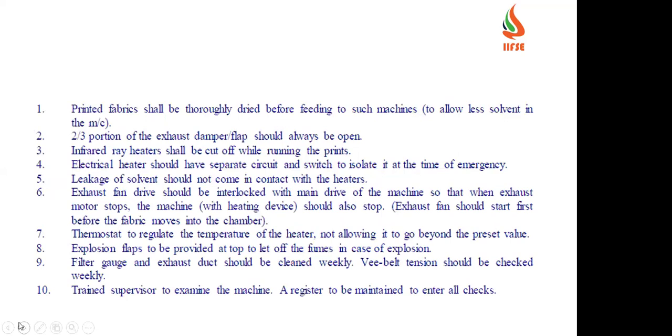Now, the printed fabrics should be thoroughly dried before feeding into such machines to allow less solvent in the machine. Solvents are nothing but flammable in nature. So before feeding into the machine, we have to make sure that it is almost dry. Then the exhaust damper or flap should always be open. So that what will happen? Whatever the emissions or the fumes which are there in the machine, it will get evaporated.